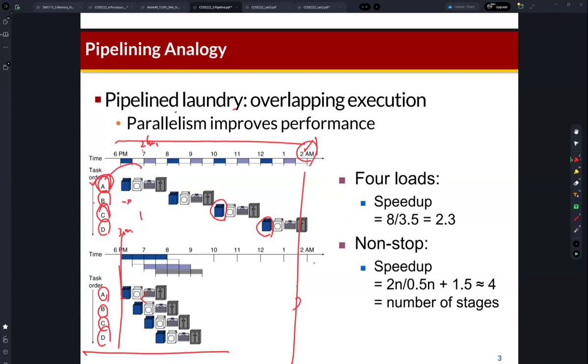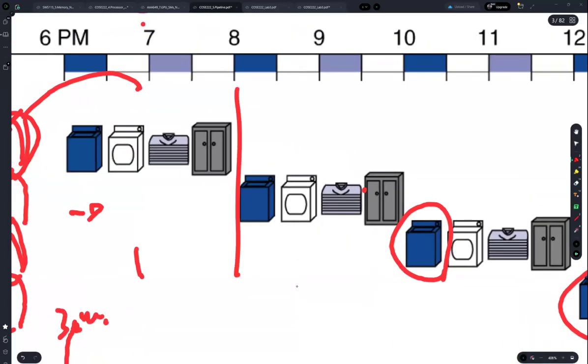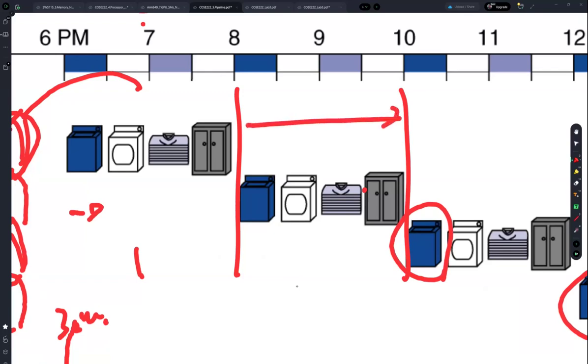It is because in the single cycle processor, this is the clock period. As I explained, it must be enough to execute the load instruction. Okay, so we need to add all the combinational delays, right? And the clock period has to be greater than the sum of these combinational delays.